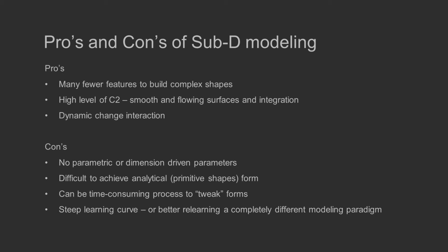The other advantage of it is that when you model in Sub-D, you're dynamically modeling. That is, you're pushing and pulling, and you're shaping as if you had a lump of clay in front of you. You would be pulling and pushing and changing patches and surfaces of that Sub-D model as you visually get feedback of what the shape is. And so, as you can imagine, quite the opposite is sometimes true in SolidWorks, where you're defining sketches and curves and you're building up to see a final result of a surface. Here you're dynamically evolving and affecting the surface.